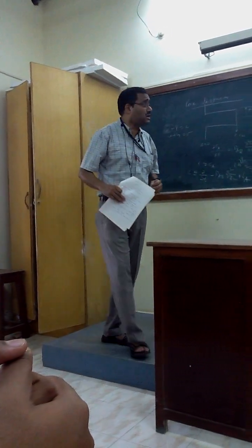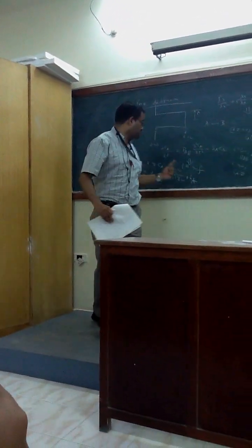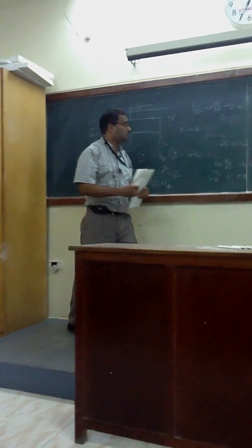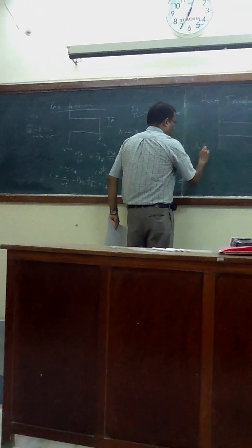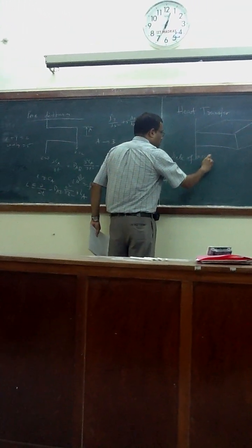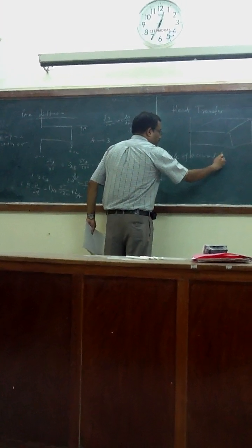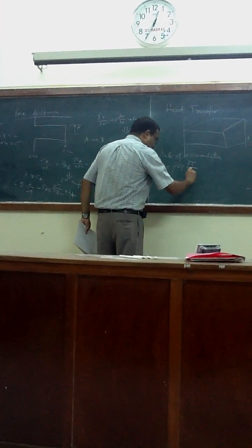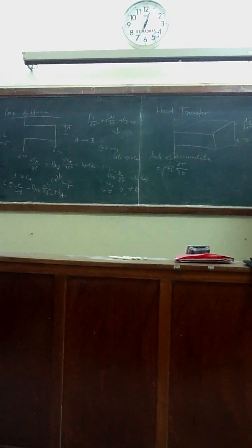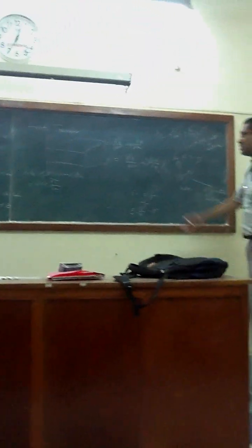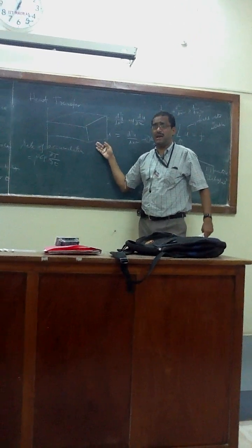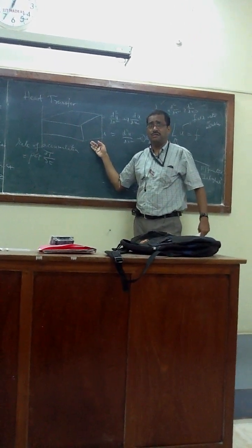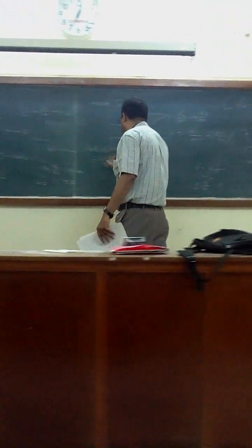But accumulation is the time dependency, right? We have seen accumulation, rate of accumulation. I should say rate of accumulation. Rho Cp, dou T by dou t. Why is it coming? There are a lot of independent variables, a three-dimensional field. The variations will be there in X, Y, and Z and T, right? So the accumulation term is rho Cp, dou T by dou t.